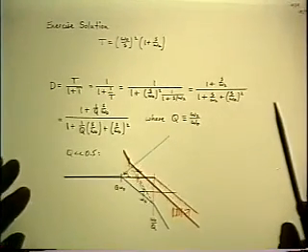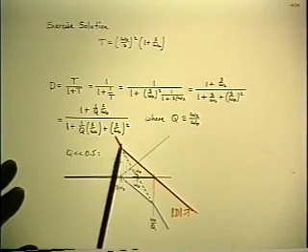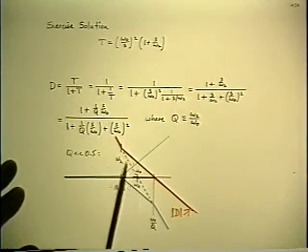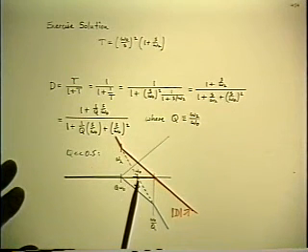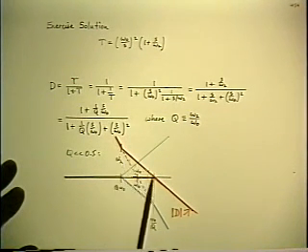If I superimpose that on top of the original picture of the loop gain, this is the loop gain coming down to extrapolated crossover at omega 0, and this is the position of the compensating 0.